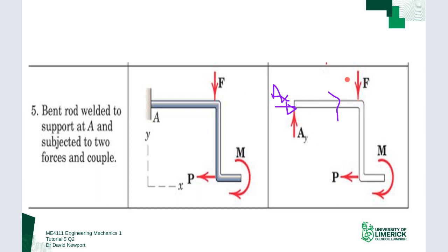Again, I could assign the direction arbitrarily, but taking a look at the forces, this is going to swing it clockwise. This one swings it clockwise. This one swings it clockwise. So chances are it's going anti-clockwise. So my reaction force would be in that direction. Sorry, not my reaction force, my reaction moment. Okay, so again, I can write that in at A. Okay, so that concludes that.